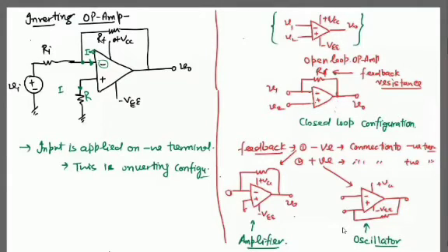Zero again, because this is an open circuit. This is an infinite input resistance connected here, but infinity means open circuit. Okay, if this is open circuit, no current will be passing through this terminal. So this I becomes zero. Suppose this branch has current I1, and this branch has current I2.